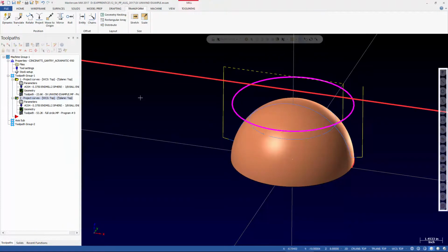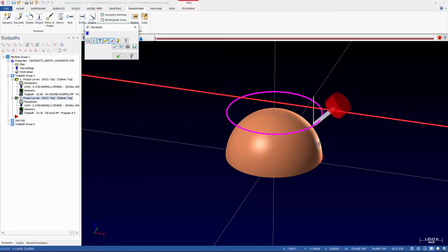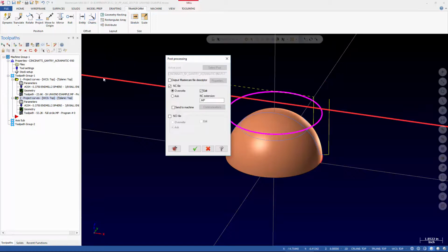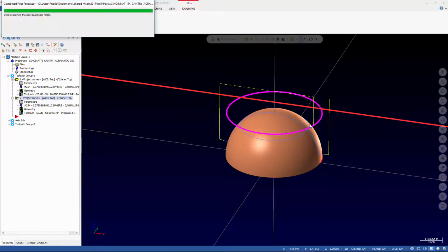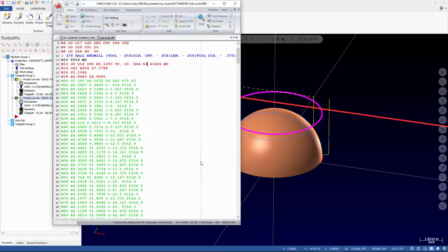We save it, and that means that this toolpath rotating this way, if we go and we check it on the machine, should be negative. So if we go and we check that on the machine and that direction is actually positive, then we have to reverse this.